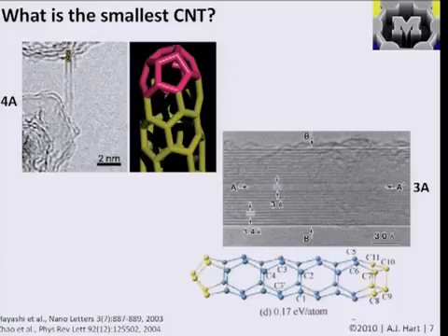Produced, and are they stable in long aspect? So they're going to be very easily degraded by air if you have defects in them. I don't know specifically how long they will last, but not only will they be easily degraded in ambient if they're this small, but they'll also be easily degraded in the growth atmosphere, which is often more volatile because it contains some hydrogen, which can easily eat away at carbon that's not in the best state.